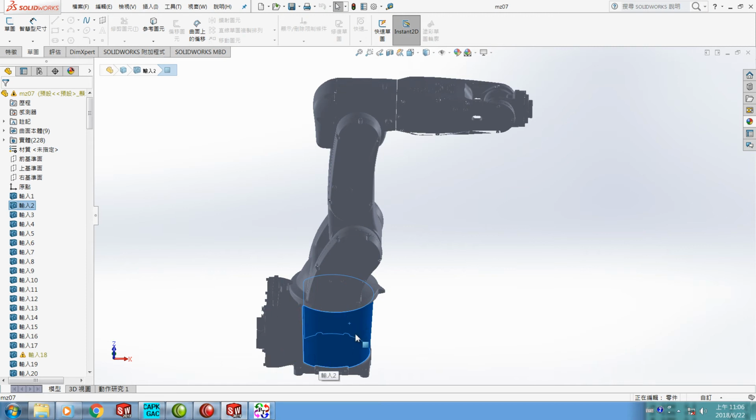The component will be highlighted, and the chosen one is highlighted in here as well. And we press input 2. You can see the whole components highlight here. That means we just keep input 2 and remove the rest of the input to get the only individual foundation, and then change the color into yellow, and save PRT file and save IGS